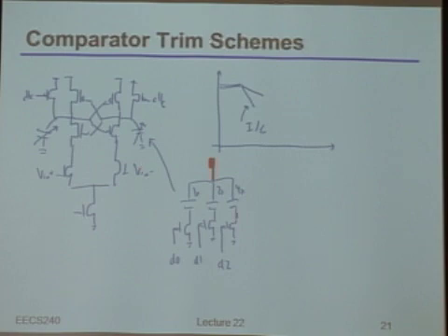So remember, these transistors always have some parasitic capacitance associated with them. So even if you turn the transistor off, there's still going to be some effective capacitance looking through that node there. So now, why is it particularly bad in this example that I gave, where I wanted this 100 millivolt range with 1 millivolt resolution? If I count the total number of unit cells here, how many capacitor unit cells do I need?